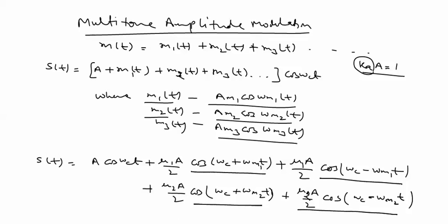If single tone, remaining terms are not present. If it is multiple tone, for each individual frequency component, two terms, upper sideband term and lower sideband term, are added to the system. One single frequency increase means two terms are added. Four frequency increase means eight terms are added.